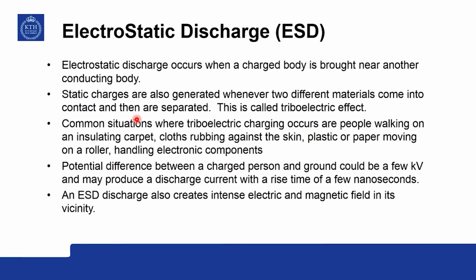Now, ESD is a big problem in the paper industry and plastic industry whenever you have material passing over rollers, because it can produce micro dimensional pinholes in the materials. So, they have to control electrostatic discharge at any cost.